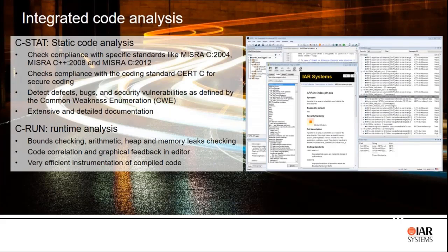So what I mentioned on one of the first slides was the solutions for code quality, code analysis tools. I mean, from static analysis to some runtime tools. This is just to give you some additional information that aside from MISRA, you can also get access to CERT C and Common Weakness Enumeration, as I said, a collection of good programming practices. And that's part of C-STAT that is integrated into the IAR Embedded Workbench.